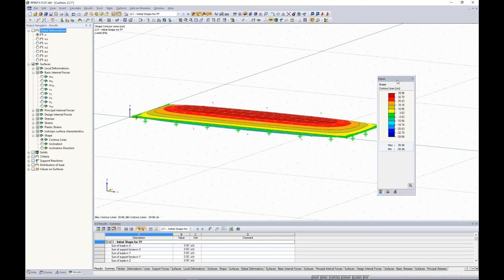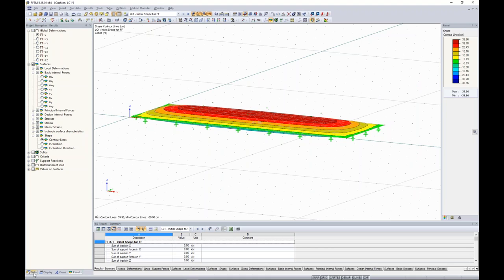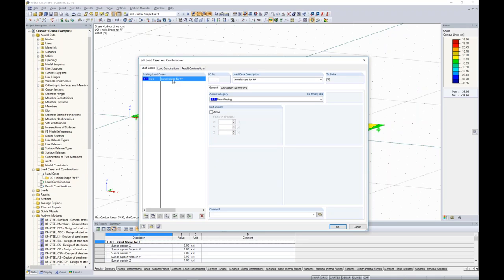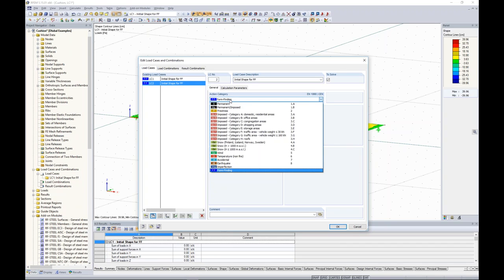And in the next part, we want to define some more loads and compare the results with the book. So let's take a look in the data dialog. We will just use load cases, edit load cases, and we want to define a new load case, or you can just copy that one, doesn't matter. And this load case should be named open cushion with pressure and snow.